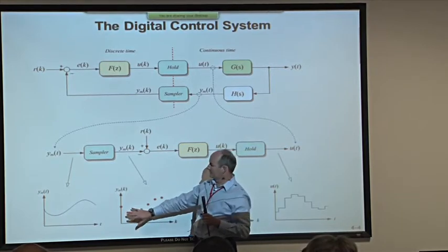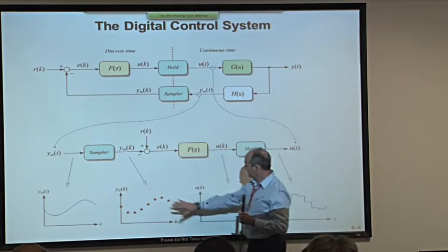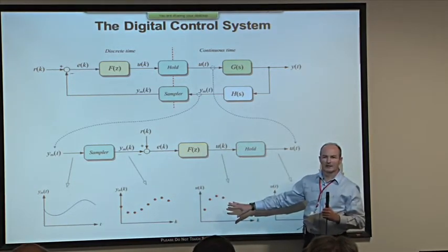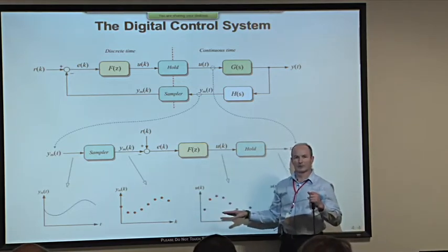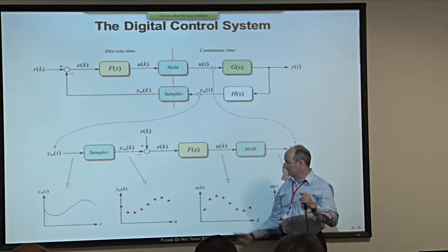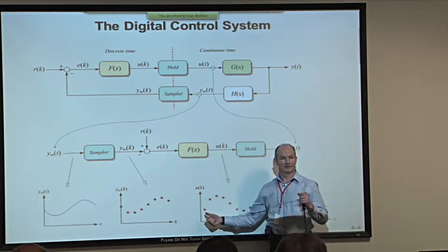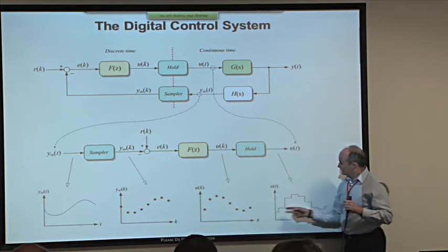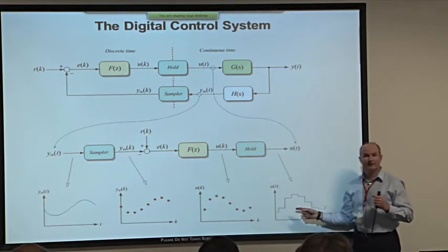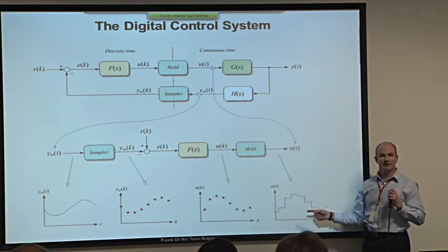That's the maximum unique frequency. It's a frequency limitation. This one, well, obviously there is a desired effect because we've designed a controller to change the dynamic properties, but there are undesired effects as well, such as time shifts, delays, and phase lags that take place. And the principal change from this one to this one is a phase lag, another phase lag.